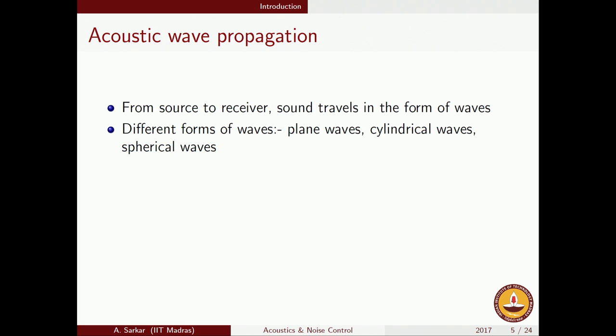Muffler design proceeds on the ideas of plane acoustic waves, but that is not the only kind of waves in which acoustic wave propagation takes place. We also have cylindrical waves and spherical waves. Cylindrical waves you would have seen as you throw a stone on a pond. These waves go out radially on the surface; these are cylindrical waves. Whereas in three dimensions you will have spherical waves. Plane waves and spherical waves we will talk about for sure; cylindrical waves could possibly be an assignment for you.